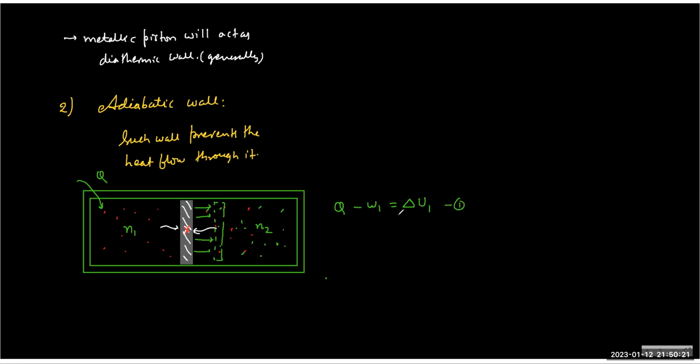But the second compartment is not receiving any energy, so it is having nothing actually. But it is getting energy by virtue of work. So the work done by the first is the energy received. That is an alternative way of receiving energy. So for one and for two, the W itself is the energy received. When you compress it, you receive some energy, but you are receiving it not in the form of heat, you are receiving it in the form of work.